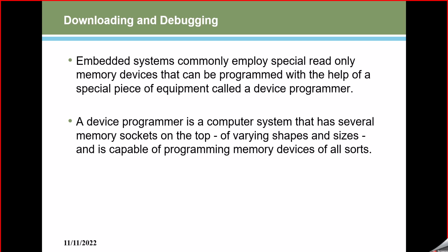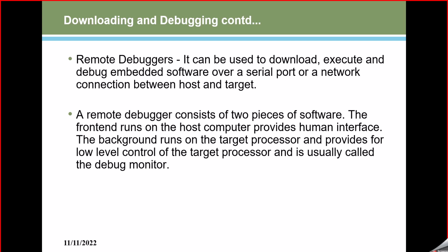That is debugging. Downloading is nothing but flashing your software inside the microcontroller. Okay, that is downloading. And we have a remote debugger also, for when your controller is in a remote location where you can't access that device. At that time you need to use remote debugging.